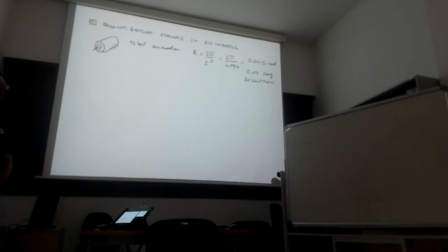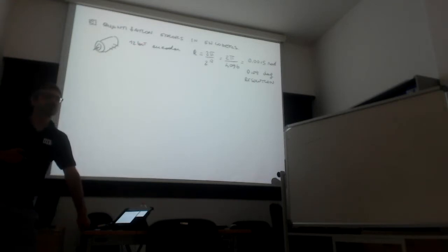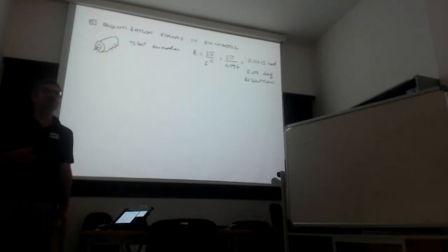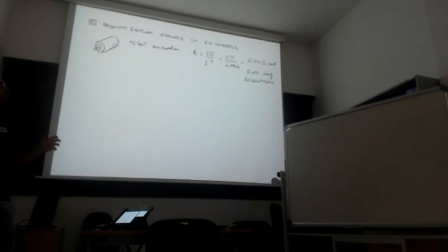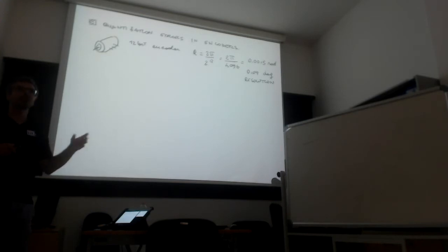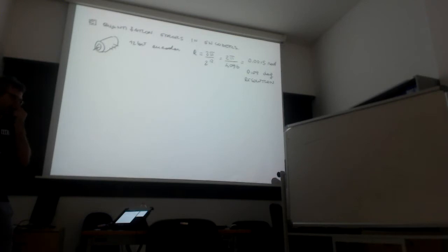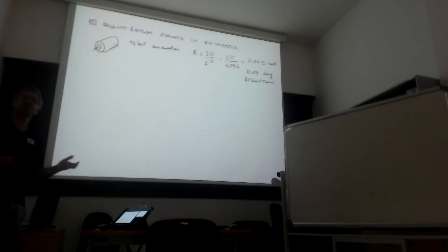And these encoders are spitting out a digital number that, depending on whether they are relative encoders or absolute encoders, will be an absolute position or a position relative to the startup moment. The number of bits of this encoder determines the resolution, that is the accuracy of the encoder, the minimum angle that the encoder is able to discriminate. For example, a 12-bit encoder is a quite crappy one.